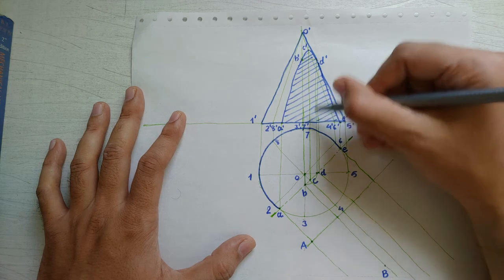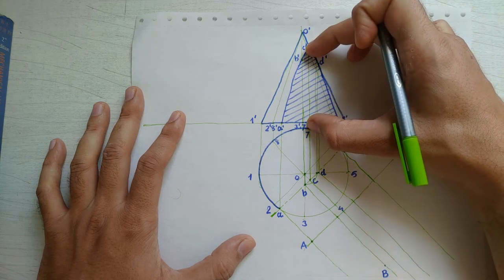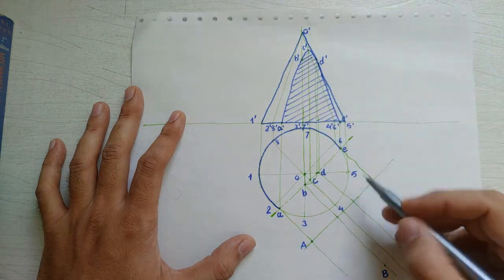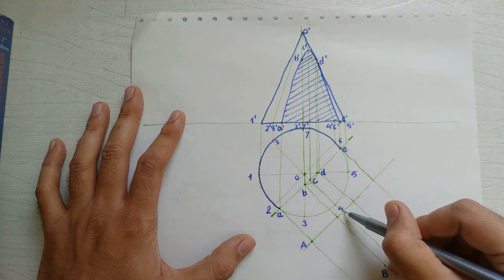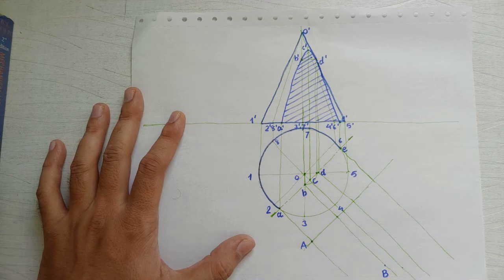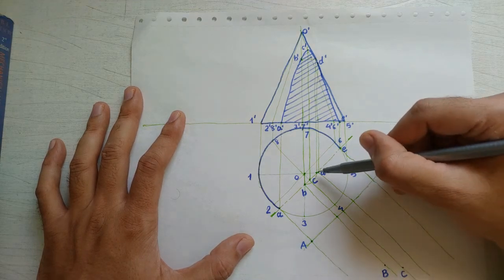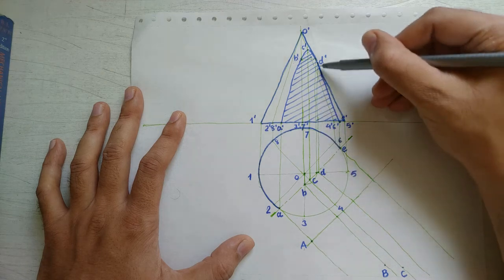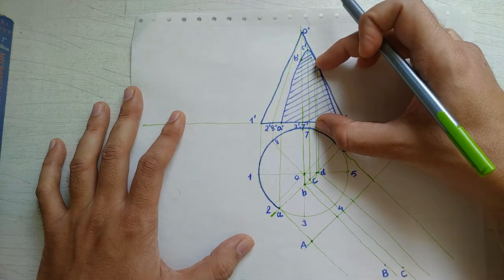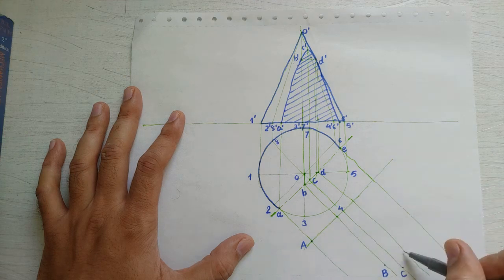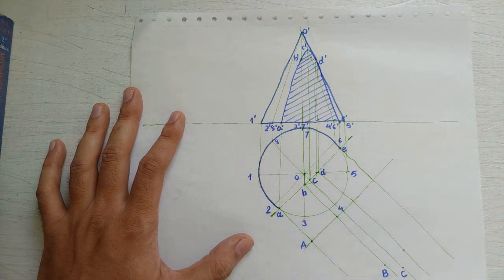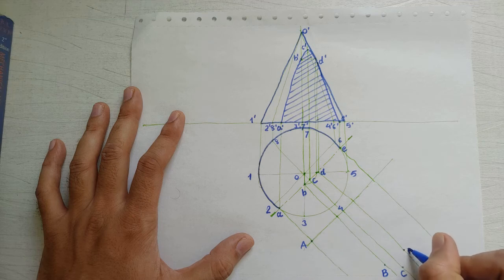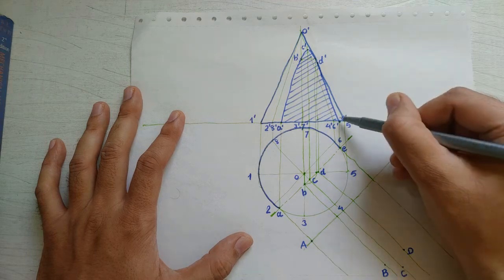So XY to C prime on this line, so that is this distance, and that distance I have to put on the line coming from C. So I will put it somewhere here, that gives me point C. Similarly, point D, so on this projection line I will measure the distance XY to D prime, and I have to put it over here, so that will give me point D. Next we have point E prime.